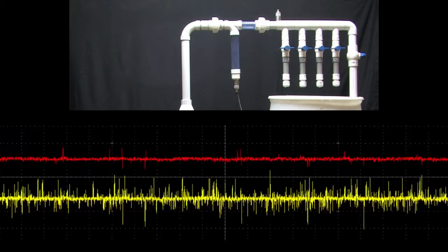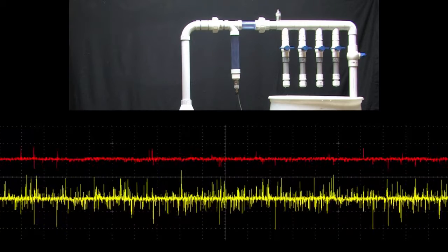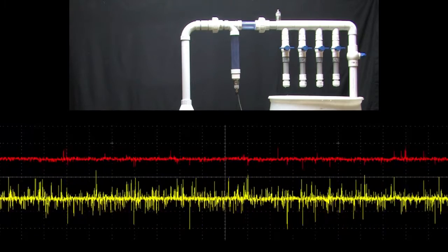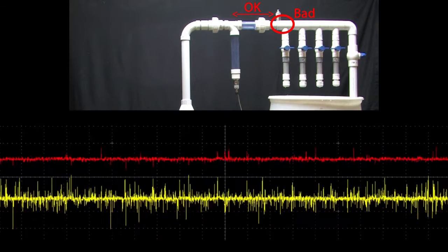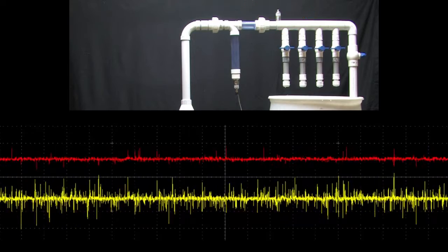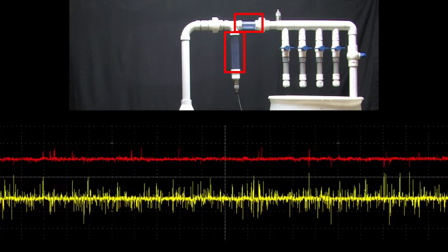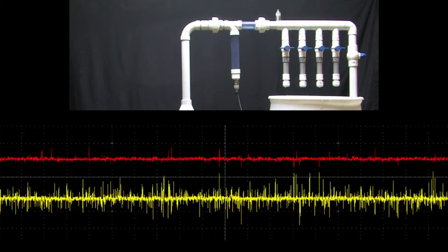And if you have to put the sensor in line like this, the 5 pipe diameter rule applies here too. Keep this 5 pipe diameters away from any bends or other disturbances in the pipe flow. These sections of pipe are clear just so I can show you that effect in action.